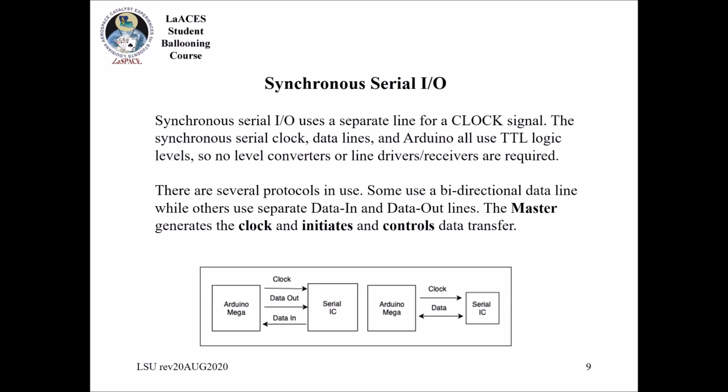And you can burn up other chips if you don't pay attention to this. And this, again, I think will be really important later on whenever you start designing your own systems. Make sure that you are reading those data sheets. Sometimes, even though a part will operate at maybe 3.3 volts, it'll say the serial port accepts 5 volt communication. Sometimes they have that, but sometimes it's not, and then you'll start putting in some higher voltage and damage the other chip. So that's what that means.